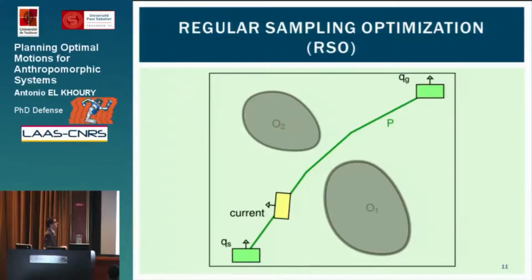So let us reconsider the path that we have obtained here. At any point of the path, we can, through linear interpolation, find a current orientation. As you can see here, it can be completely arbitrary. So we define additional orientations for the bounding box by keeping the x and y coordinates. We define a front orientation, which is tangent to the path, and we define the two possible lateral orientations, where the direction of the bounding box is orthogonal to the path.